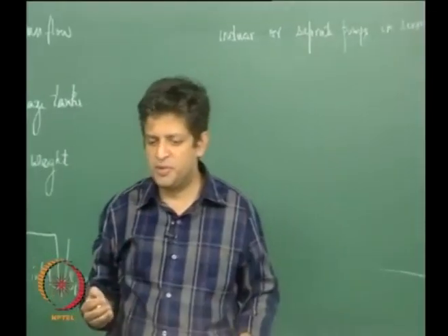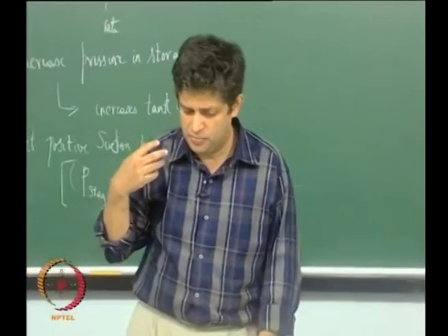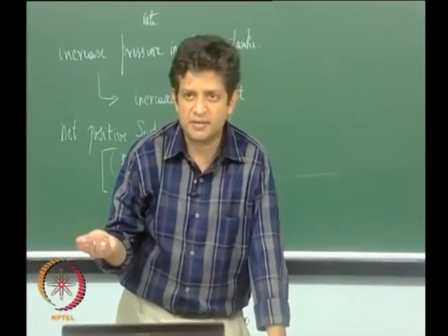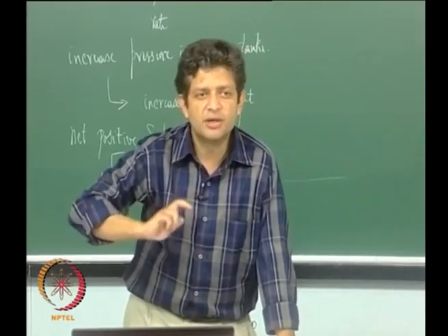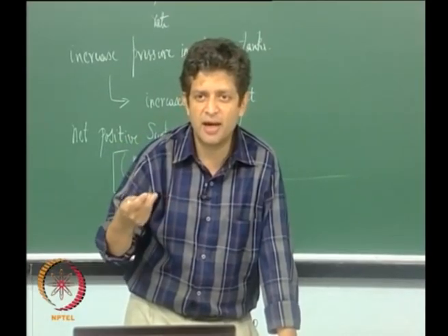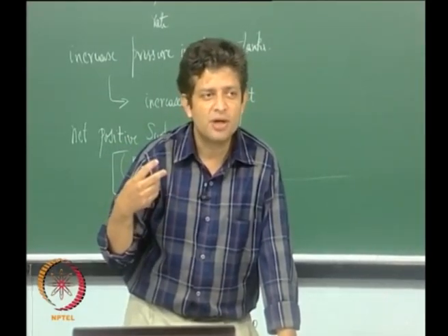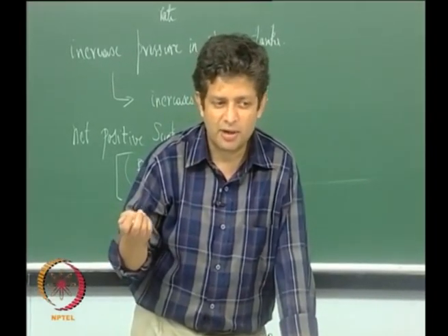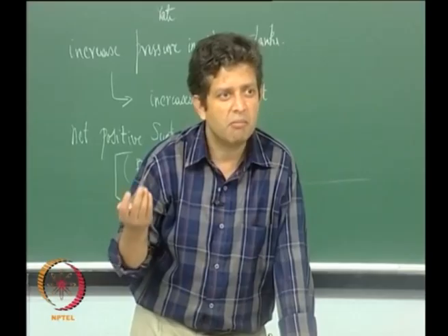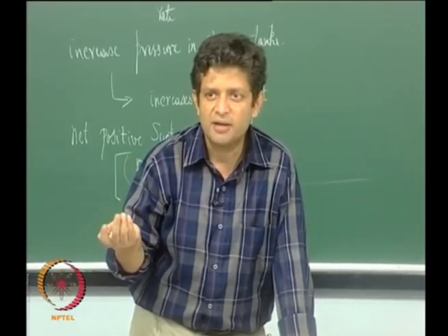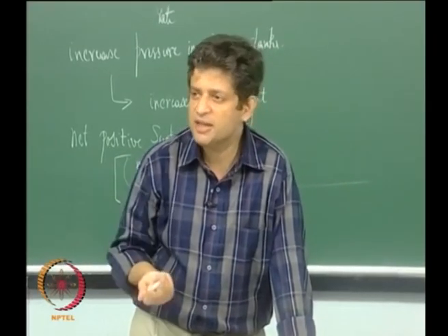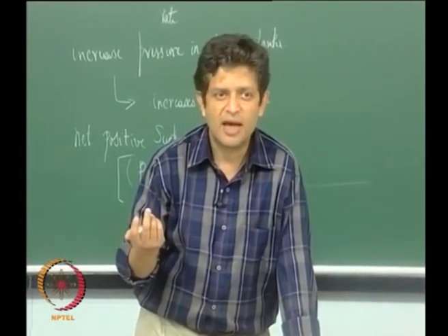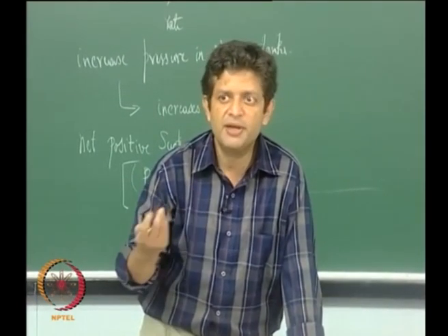So, the way pumps operate is like this. There is a rotor and a stator, right. In the rotor you rotate it at very high RPMs and therefore you give it kinetic energy, or in other words the velocities are very high, which is recovered in the diffuser stage, or the stator stage, as pressure. Fine.